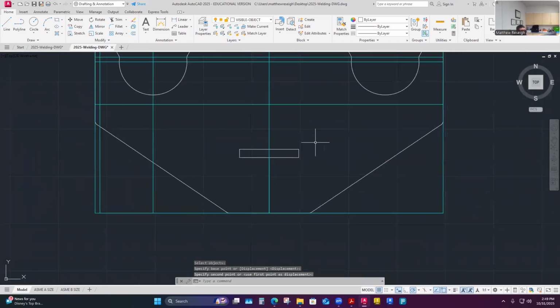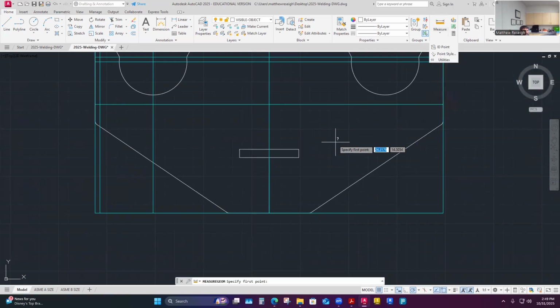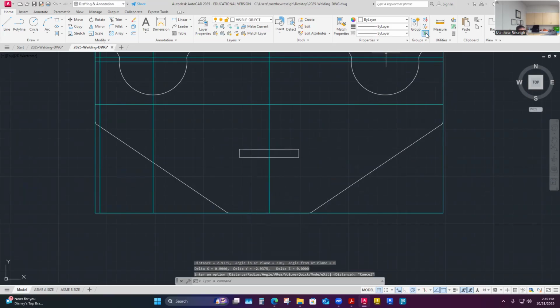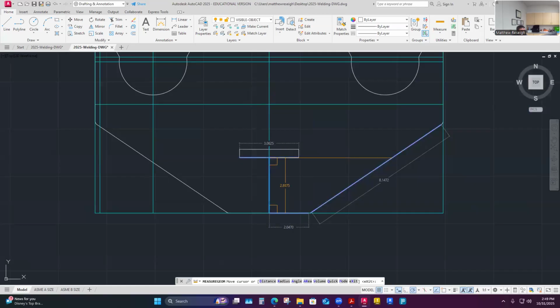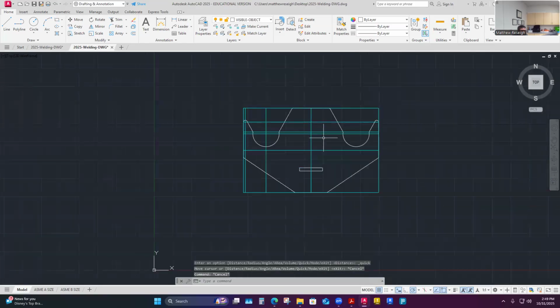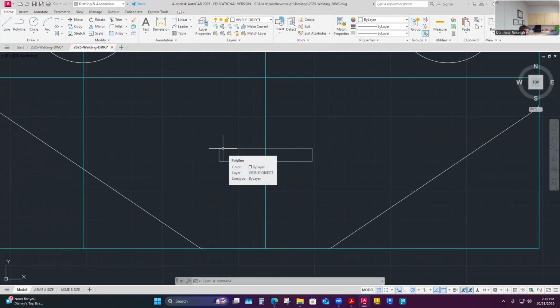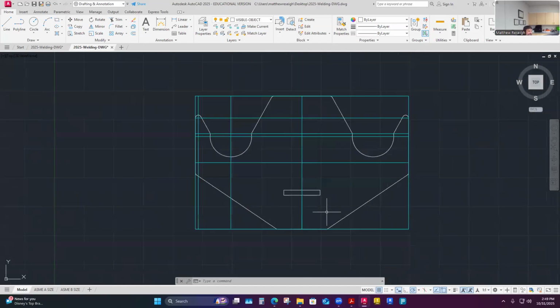So I just moved it, and once I click that, the command exits, and then I could double check that. I could measure this distance. Distance measurements are from point to point, 2.9375. That looks correct. The geometry of it inside, quick dimension, yeah, 7/16 by 3 and 1/16. So cool. This is the actual, and I think we kept that as a nice sharp inside corner. It has to slip over that rectangular pipe stand material. Done deal. So enjoy that.